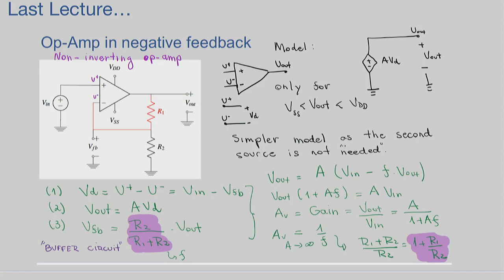Then we saw that by putting the digital to analog converter in the middle of the speaker and the digital signal, we got a loading effect where the voltage output getting to the speaker was actually lower than the signal we were giving to the DAC.